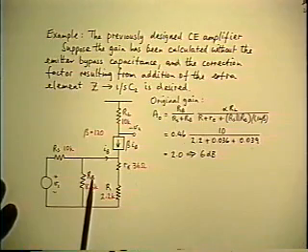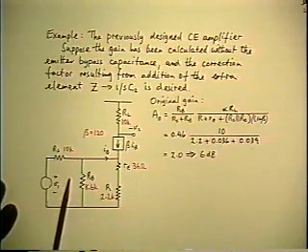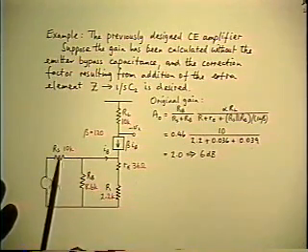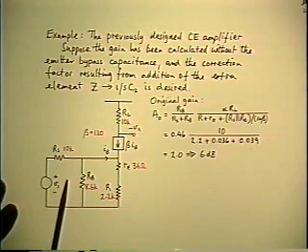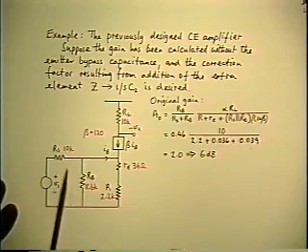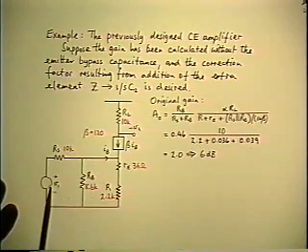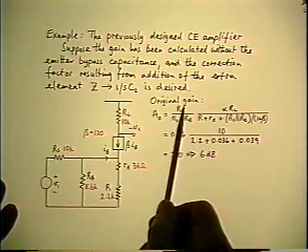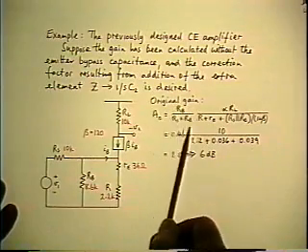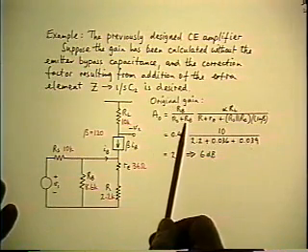So, let's take the approach of removing the first loop by Thevenin reduction. So that gets rid of the RS and RB divider directly as a multiplier on the Thevenin equivalent source voltage, so that divider will show up as a multiplier in front of the gain.